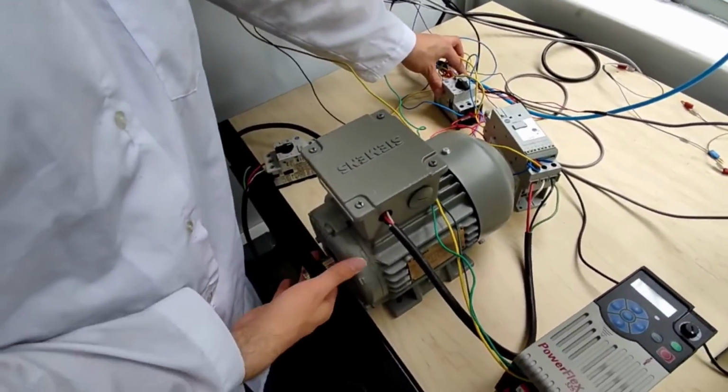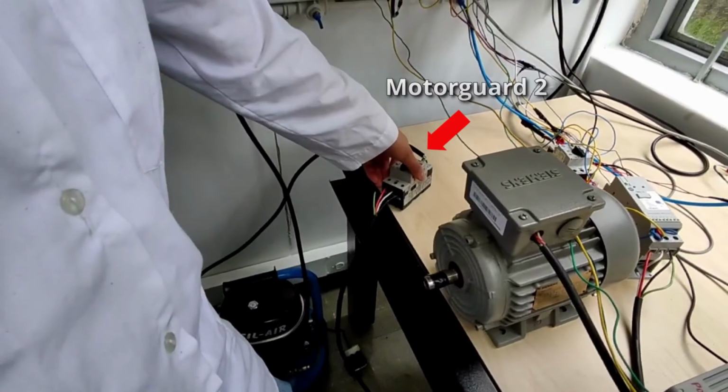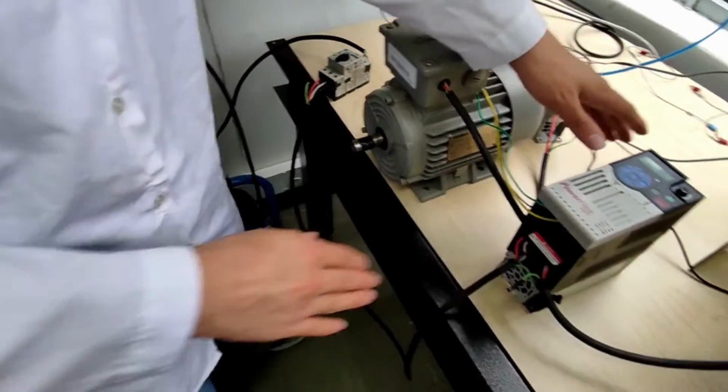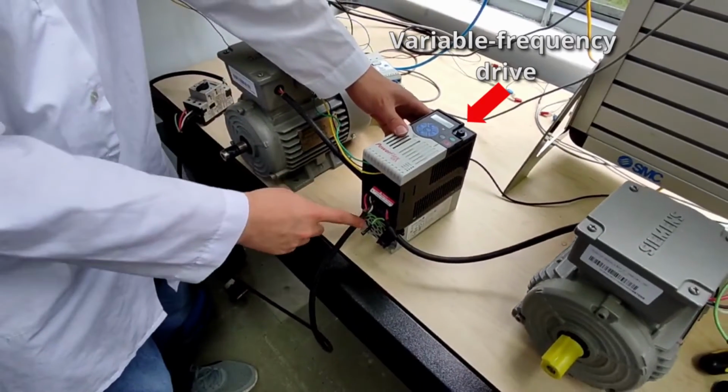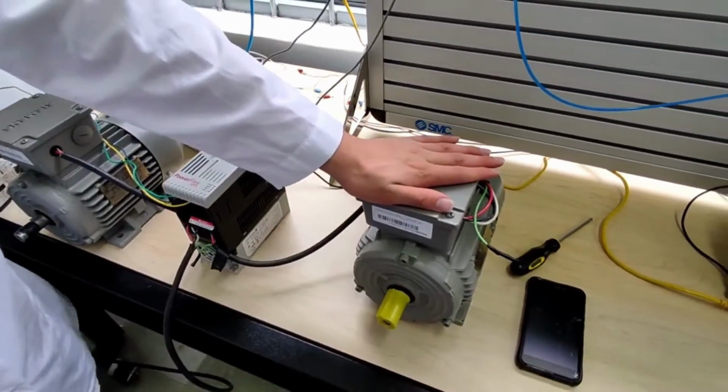The second engine that we can appreciate is a motor that is controlled by the variable frequency drive. This represents the pallet output conveyor. This system starts with the magnetic starter, then the variable frequency drive that allows us to control the frequency given to the engine from 0 Hz to 60 Hz. This is possible with the analog output of the PLC from 0 volts to 10 volts.